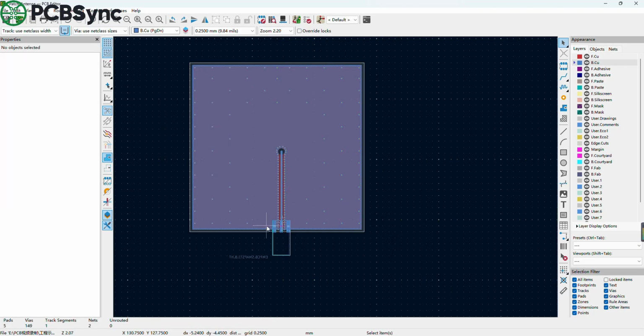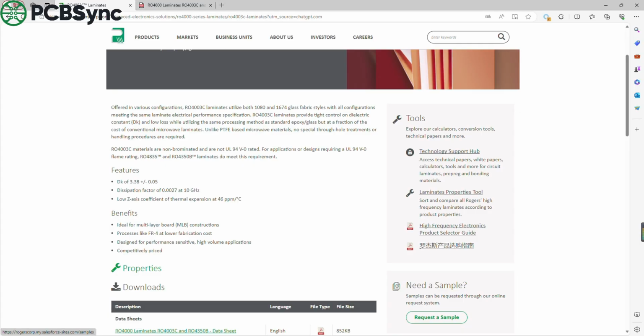Third, you need to check the feed position and matching. The feed point of a patch antenna affects the input impedance. After changes in material and dimensions, both the structure of the feed point and the length of the feed line need to be readjusted. Finally, you still need to confirm the resonant frequency, return loss, gain, and radiation pattern through electromagnetic simulation and physical testing. You can't just rely on theoretical formulas to go straight into mass production.